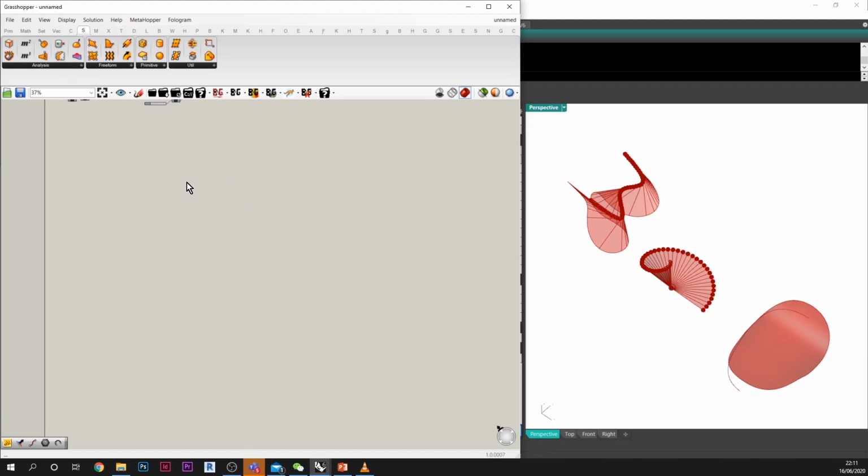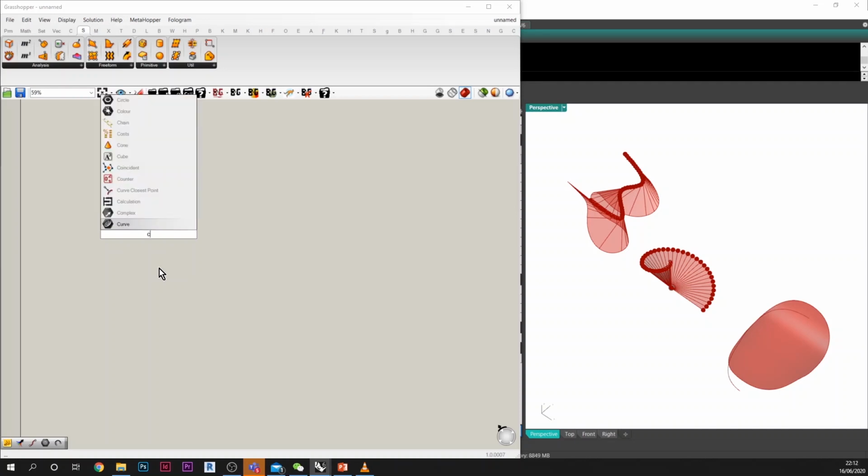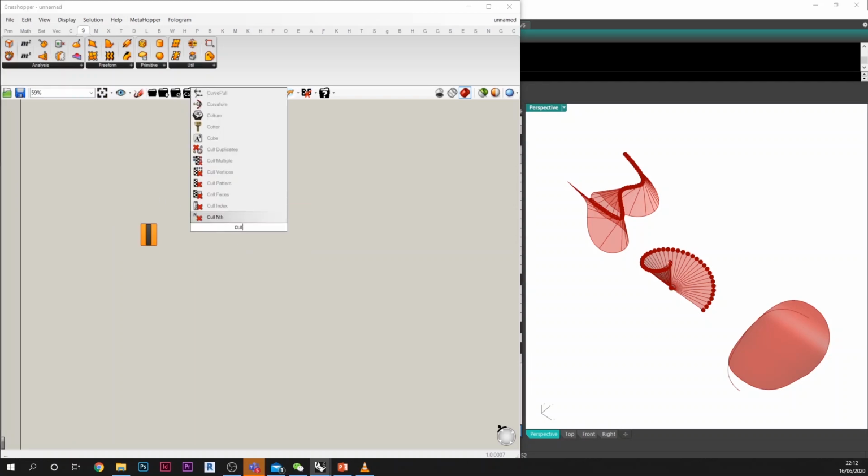The first one is just by computation of the Gaussian curvature. This will be quite simple because it is already included in Grasshopper, and it is called principal curvature. You also have the curvature analysis, which is already included, but just to explain, we will do it more manually